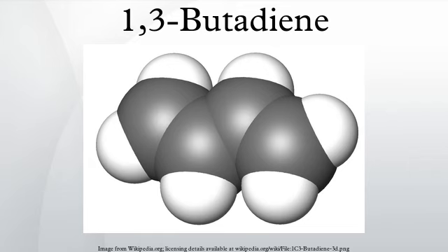Storage of butadiene as a compressed, liquefied gas carries a specific and unusual hazard. Over time, polymerization can begin, creating a crust of solidified material inside the vapor space of the cylinder. If the cylinder is then disturbed, the crust can contact the liquid and initiate an autocatalytic polymerization. The heat released accelerates the reaction, possibly leading to cylinder rupture. Inhibitors are typically added to reduce this hazard, but butadiene cylinders should still be considered short shelf-life items.